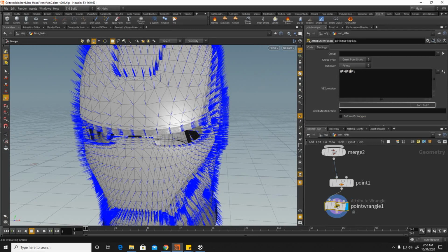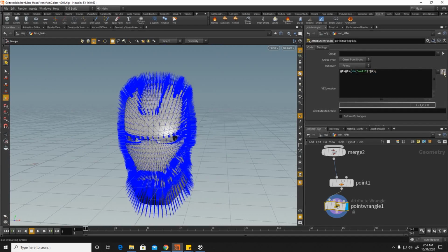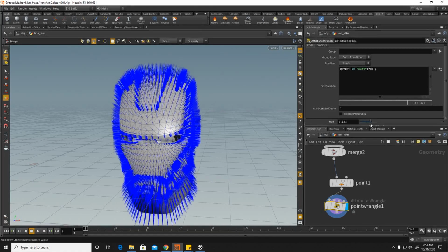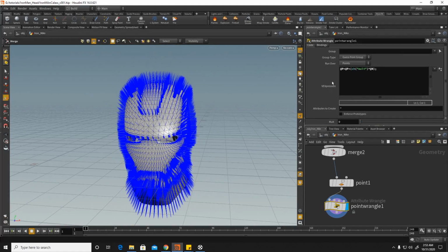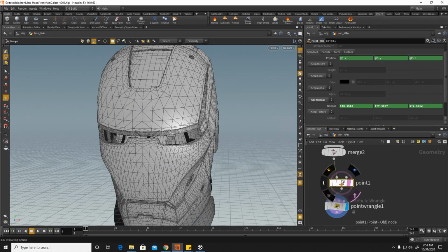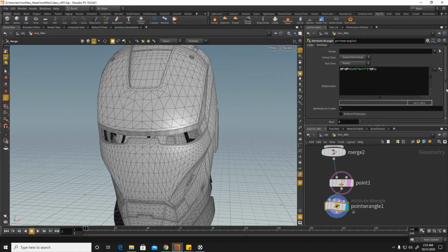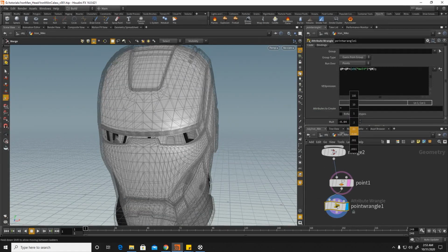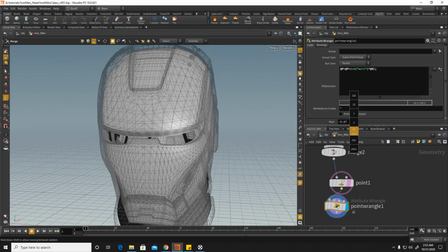So for this I will ramp this normal. I will take ch, and I will take a float multiplier, and I will multiply it with normal, and I will make the whole expression in brackets. So you will get this type of slider. For making it go inside, let me turn off this visualizer, template this, and visualize this. If I make this value go lower than 0, you can see this geometry is shrinking inside.